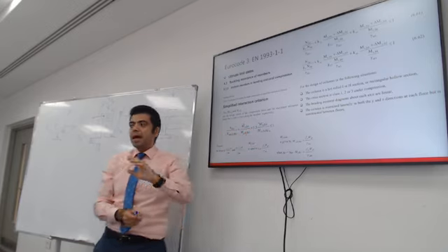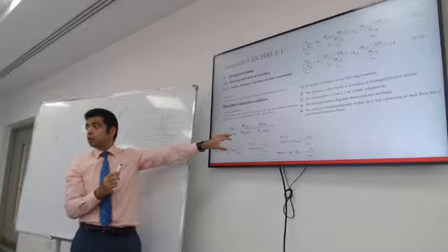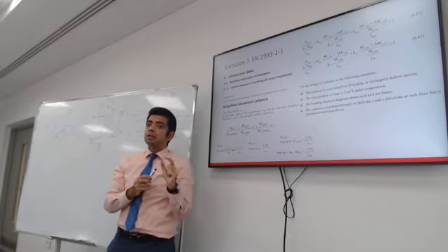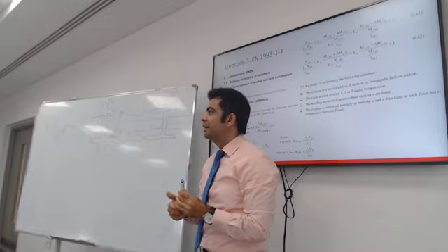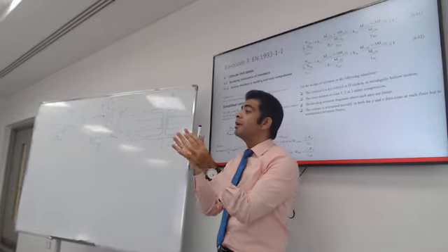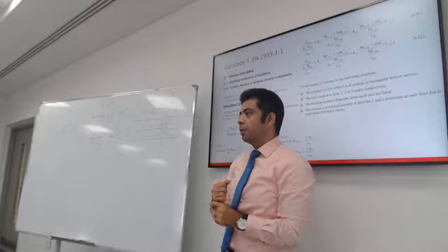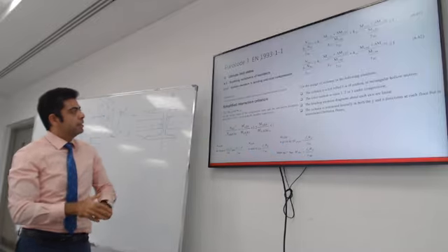So does that mean that I can apply an axial load that is very close to the full axial capacity of the column? No, why is that? There you go. It's not going to leave enough room for the column to resist moment about x and moment about y. That's exactly why. Excellent. All right. So how do you calculate these factors?